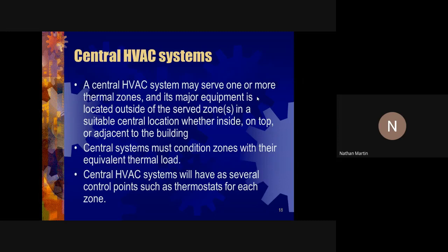We don't want to buy a bigger unit, another unit, or a split unit. So what persons do is modify their ducting and start to take from the central unit to a new location. What this does is add more load, because every new space you add, you can consider as adding load to the system.